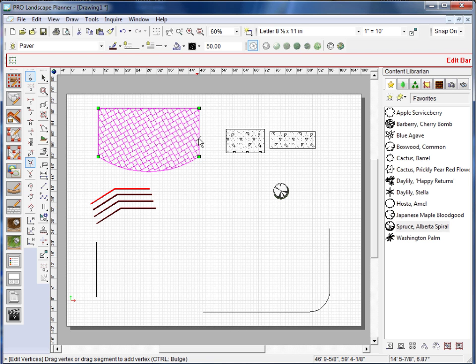Okay. Now if we were to click on this line between the two green points here, it will just add another point, and there will be straight lines in between that point. But if we want to add an arc like this, we simply hold the Control key down on the keyboard and then click on the line and pull it out a little bit and then drop it, and then it adds a nice smooth arc in between those two vertice points.